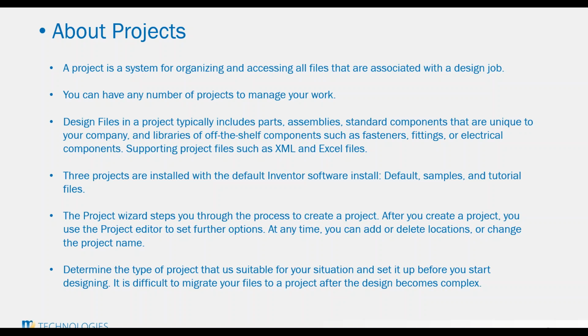When Inventor is first installed, there are three project files: the default project file, the sample project file, and a tutorial project file. In order for Inventor to load, it has to have a project file already active. So they have developed a default project file which will automatically load. In some cases, people will install Inventor not realizing what a project file is and just immediately start working.